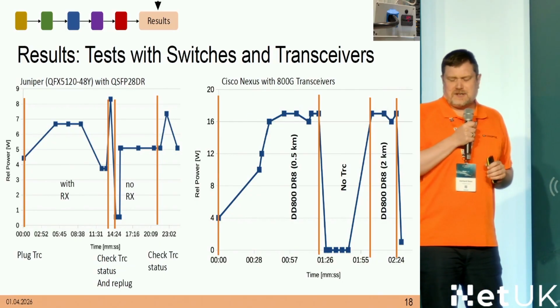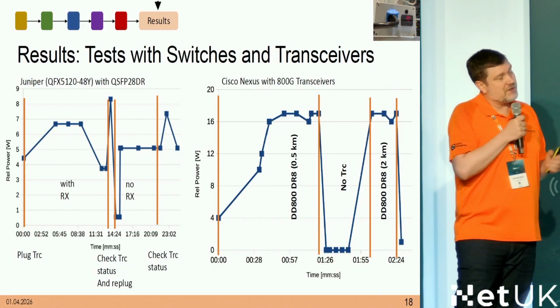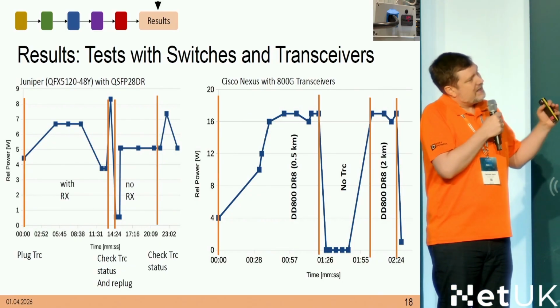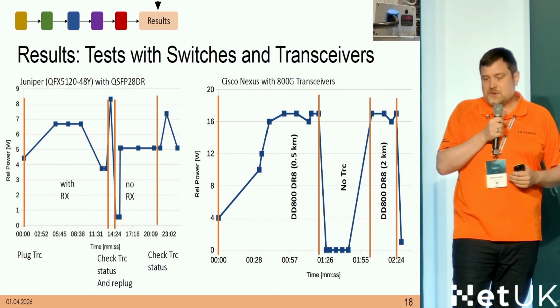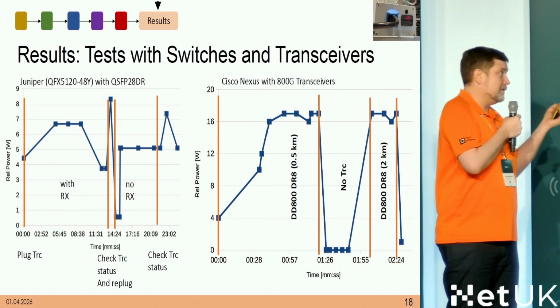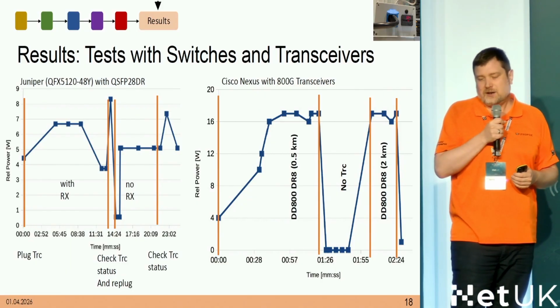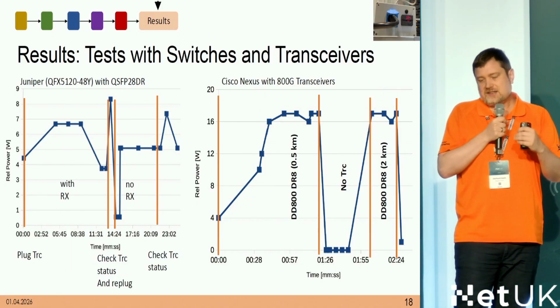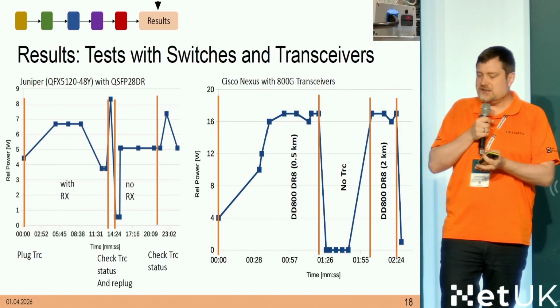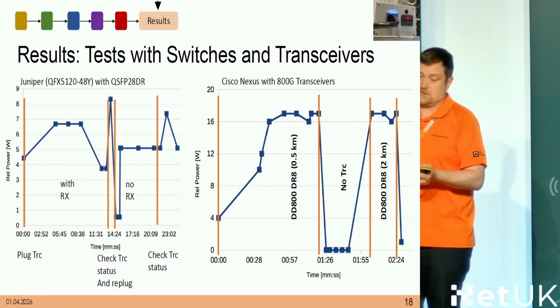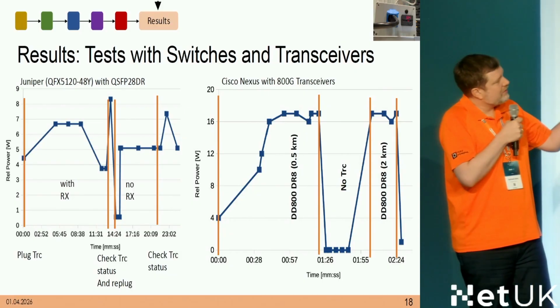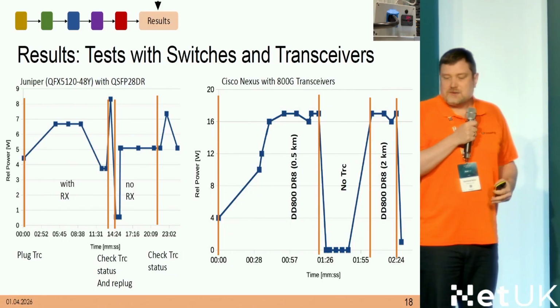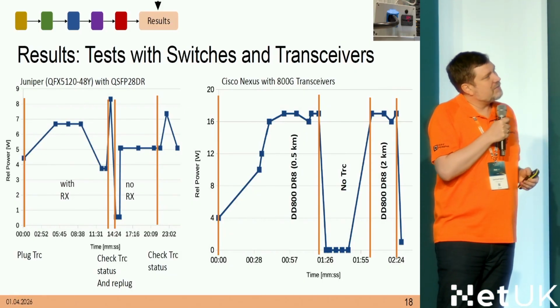And I could observe that even though it would consume around 3.5, 4 watts, it goes up to almost 7. Why? Because you have some management overlay, obviously, inside that ASIC that is running in the switch. And as soon as you open the management surface to a serial port, you're connected, it goes up because it also has to do the processing for this terminal.